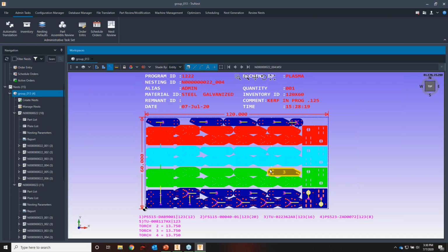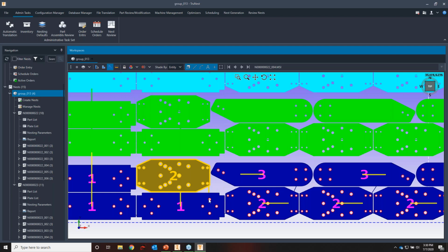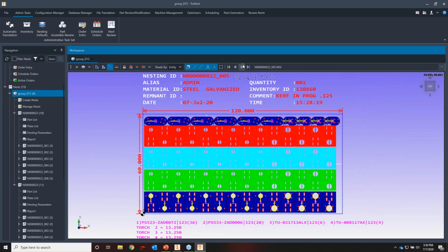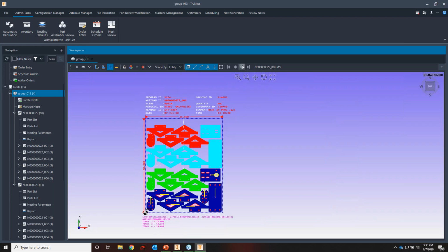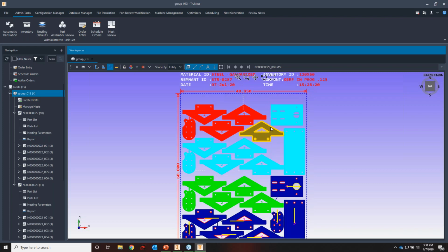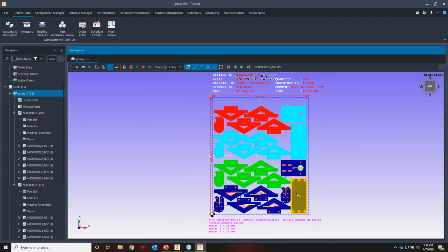So all the while, we're still doing the sheet cutting as well as the reduced pierce logic on all these parts as well. See if we've got some different results. Very similar result there. And then here you can see some of that as well. In this case, we're going from 4 down to 2, and you can see some of the part integration here for the torch reduction. So these 2 parts are going down to 2 torches, and it's integrating with some of the space.